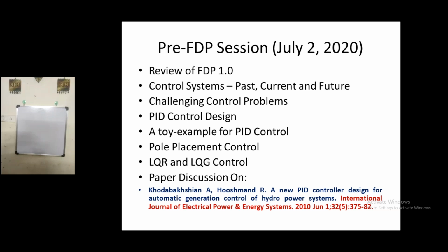Then we discussed a particular paper on LFC control where there were two PID controllers. We saw that Kundur used only integral control. If you use PI control, what are the advantages? We compared the same and used auto tuning, one-minute tuning, and saw how to get the desired response in one minute. We compared that with several papers where people used the bacteria foraging optimization method, PSO method, and so on, and we saw that it was able to get better results in one minute.